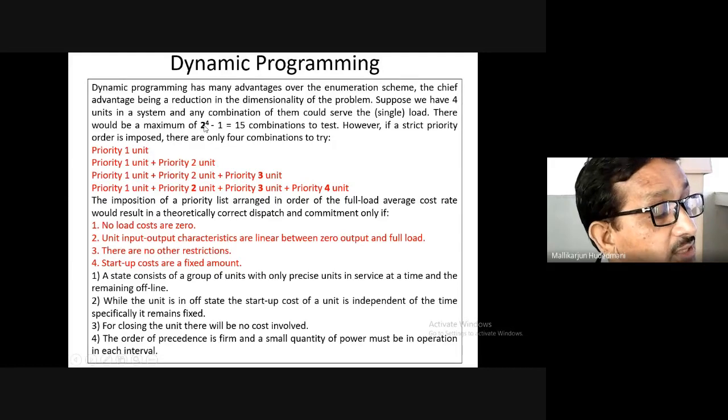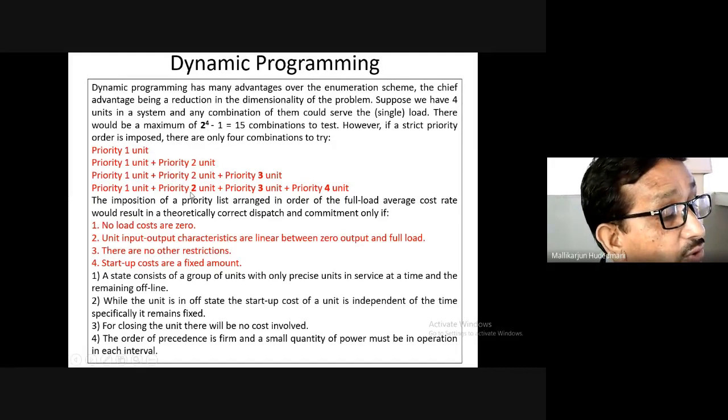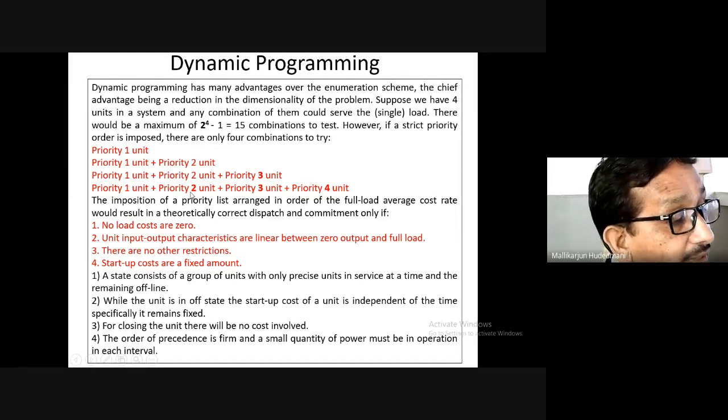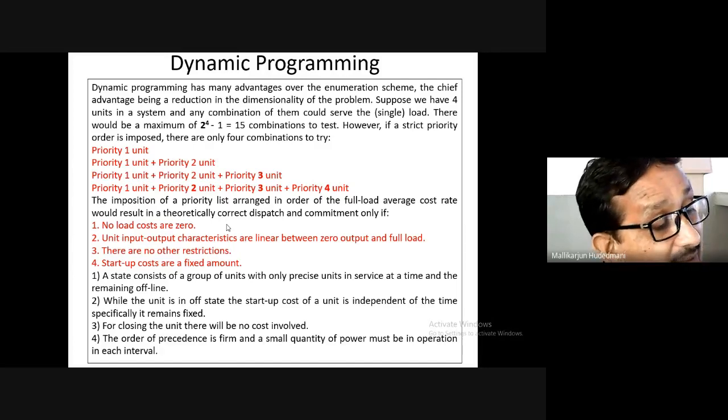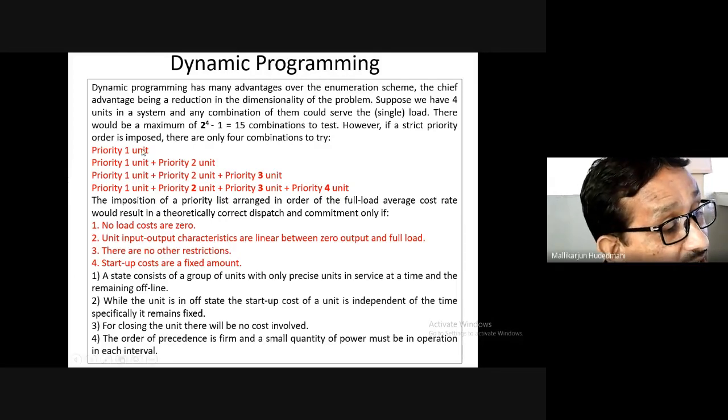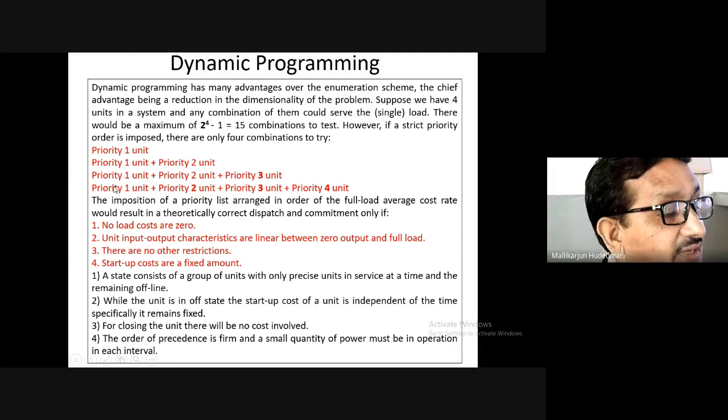So here I took a case: if there are 4 generators, how you combine all the 4 to meet your requirement using the dynamic programming method. This is just an outline. Take decision number 1, work till its max capacity. Certainly you are left with a load shortage, a generation deficit. You combine with another one, which is the second decision. The second decision should be optimal on the outcome of the first, so that it is better in the next comparison. Likewise, only n decisions are left here.